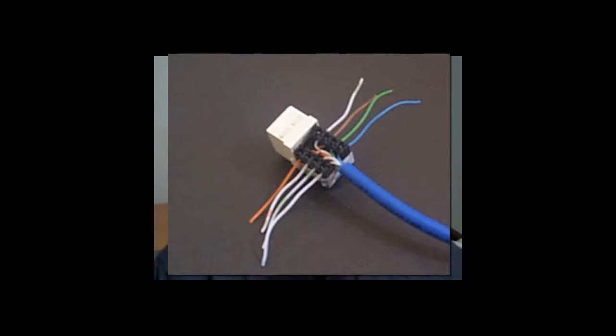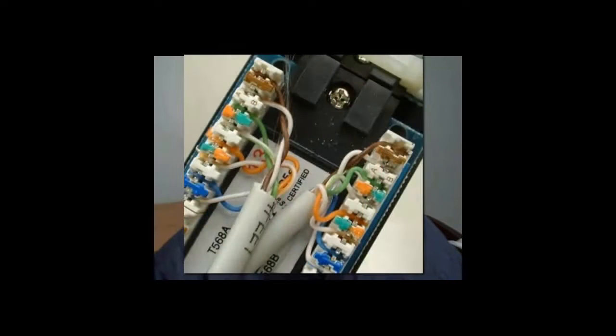You just need to take a moment to decipher the color code on that particular jack, and you place the wires, all 8 wires, usually 4 on one side and 4 on the other, where they can be securely engaged, and use a spring-loaded, what's called 110 punch tool. Using compression, using a spring, pushes each wire in. This sort of fires each wire into a V-shaped connector, and we make a secure electrical connection that way.